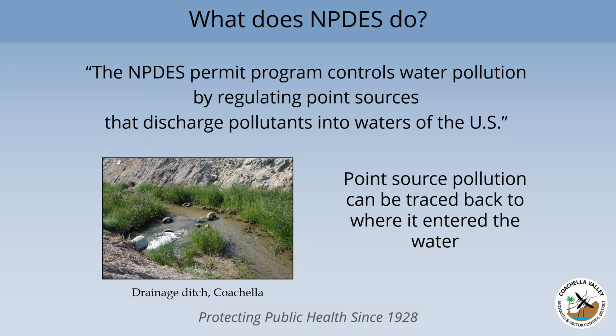The other kind of pollution is called non-point source pollution. And so this is more easily thought of if you think about runoff that's coming off of people's yards. Perhaps there's some pesticides that are on some residents' yards, and those all get washed off in the rain. They all come down into a catch basin. You test the water that's in the catch basin, and you can find that there's pesticide there, but you don't necessarily know which of the houses it ended up coming from. And so you have to do a little bit more digging to be able to figure that out and to make those kinds of control efforts to prevent pollution from entering the water. Much different than what you're doing with our applications where we know what came out of our nozzles when.